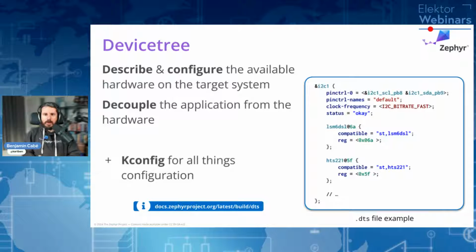There are lots of modules, lots of functionality that is optional in Zephyr, which you may or may not want to use. Do you want to have logs available in your final application? Do you want to have an interactive shell in your final application? How much memory do you want to allocate to each and every task? Rather than hard coding things in your code, or playing with header files and having hard coded defines in there, there is an entire configuration management system, which is called kconfig.